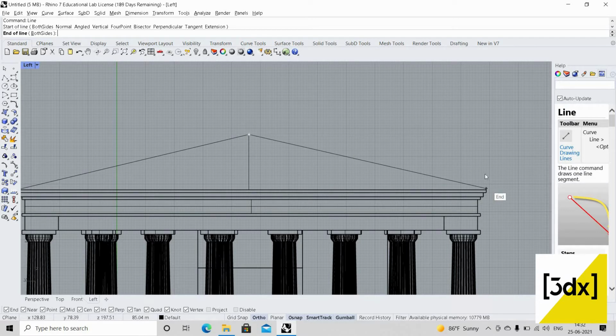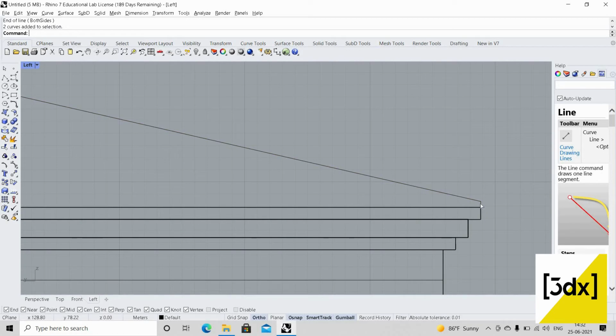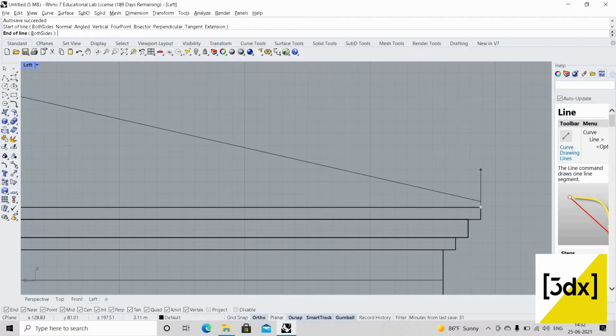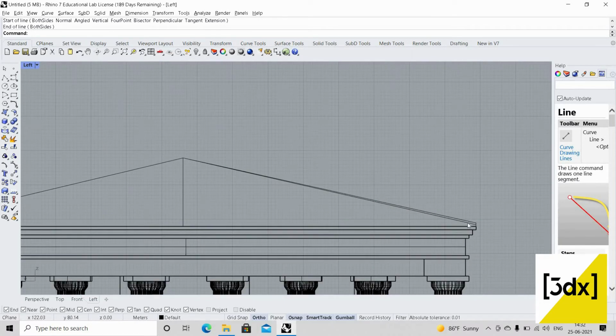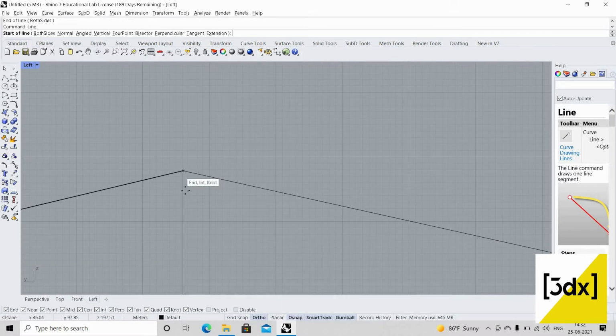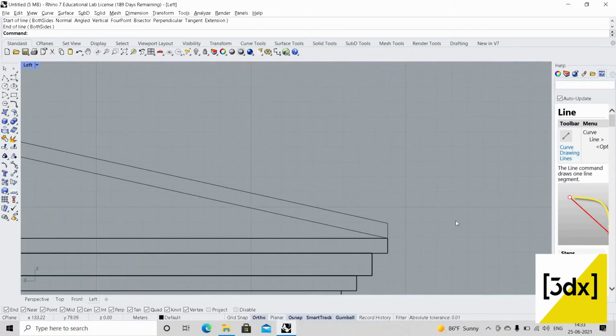So the vertical line has been drawn. This is a normal roof, but I don't want this. I want a little bit of height raised, and I want it to be projected. So I'm just drawing a straight line with an approximate value. Yeah, this is fine. I'm joining these two ends and deleting the line which I drew before with the base of this. I want to add a line, but I don't know the dimension, so I'm drawing the same distance which I drew there. So now I'm drawing a line with the base of this. So you get an equal.